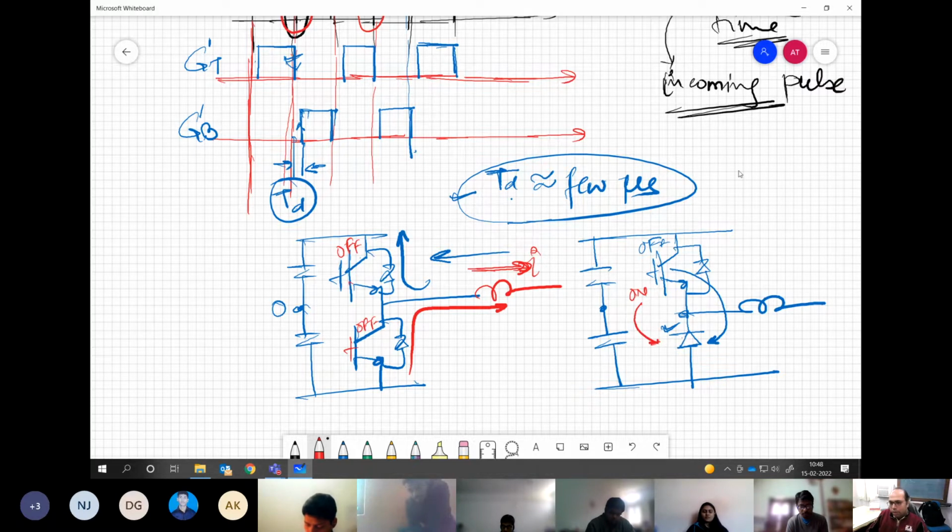So in case of a voltage source converter, the current transition is always from device, let's say IGBT, to diode, or vice versa. It is never between two devices directly. It will not happen that this is conducting and then this is getting transferred to this directly. You understand my point? So you are taking from, let's say, the device, giving it to the diode. Then based on the direction, if required, when this device is on, it will take over that.